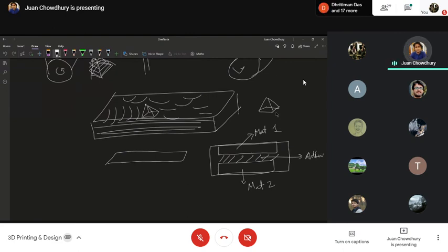Okay, so with a sufficient amount of laser power, it will cut through the object, the slice, but with just a little less power, it will melt the adhesives, and the layers will get stuck one after another. Okay, this is how composite material fabrication can be done through this LOM process. Well, that's a quick overview.